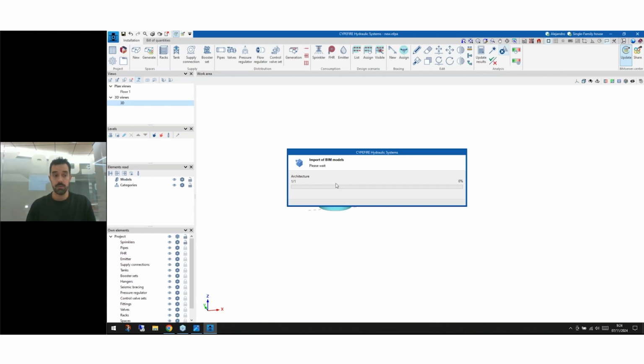As I said before, the only thing we need to import a BIM model and to start to work is that this model has to be defined with spaces. Because right now, we have completed the first 2 steps with the standard and the Open BIM database catalogs, but this was because we didn't have these spaces.